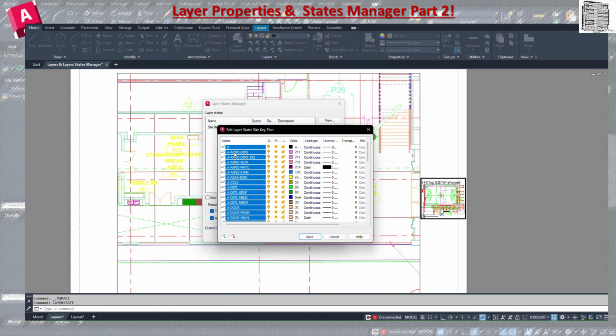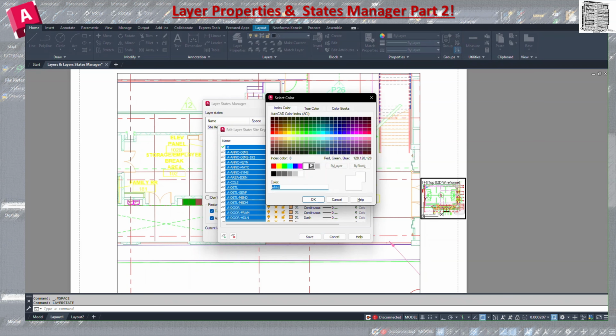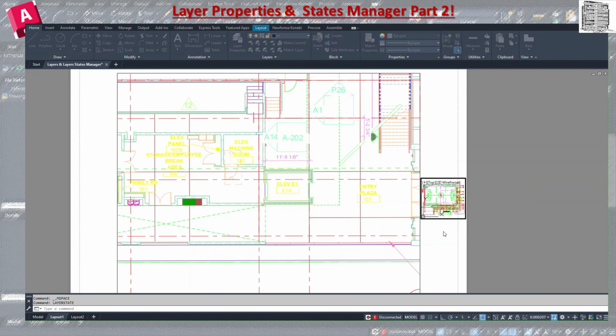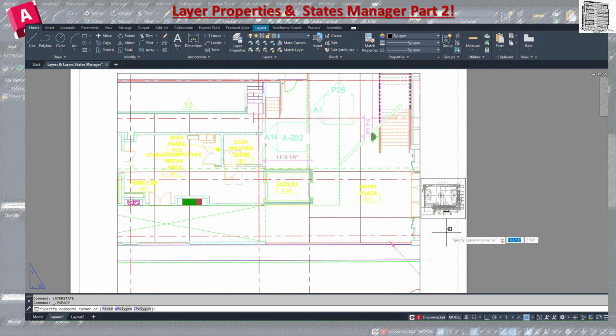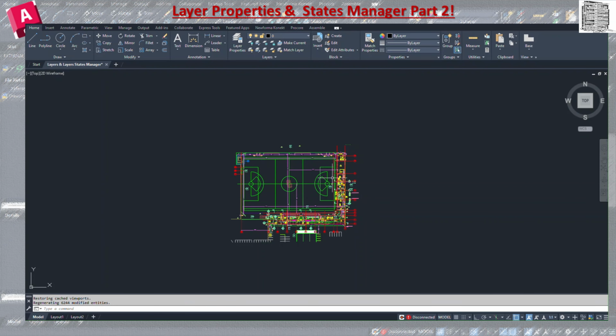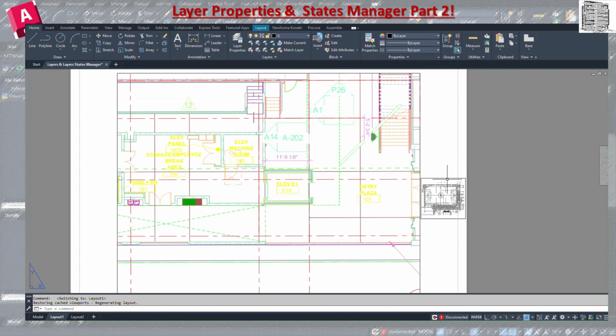So what I'm going to do, I'm going to select all. I'm going to change this color, I don't know, to this gray. Save, restore, and I want to double click outside. And then you can see in like a second, let's just see what's going on. Yeah, it turns everything into gray. So it hasn't changed the color of my actual model. If I go back to my model, let me click on it, still has the same attributes, colors. If I come here, only dealing with the viewports that I created because I create one settings for the viewport.